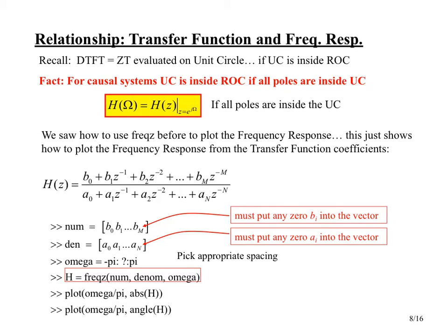And so now we want to link the transfer function to the frequency response. Remember I was saying in a couple of notes I had previously that we use the transfer function and z-transform ideas for a lot of design and analysis of how a system's going to behave. And then when we do finally want to think about what this is really going to do to a signal, we switch back to frequency response, assuming that the system is stable.